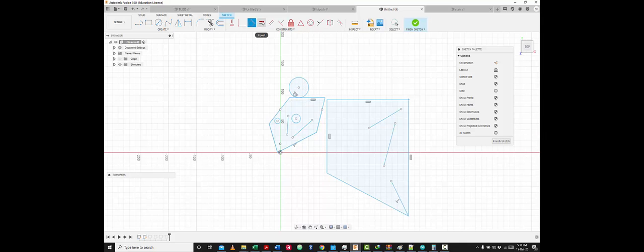The next one I want to talk about is the equal feature. So I can use the equal feature to make two lines equal to each other. And I'll be using that in drawing the tripod. So I can make this line and this line become equal to each other by clicking on this one and that one. And then you notice that they become equal to each other.